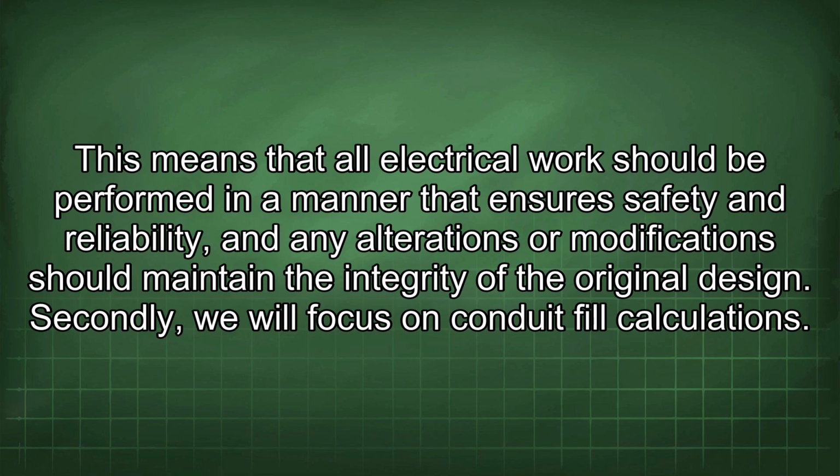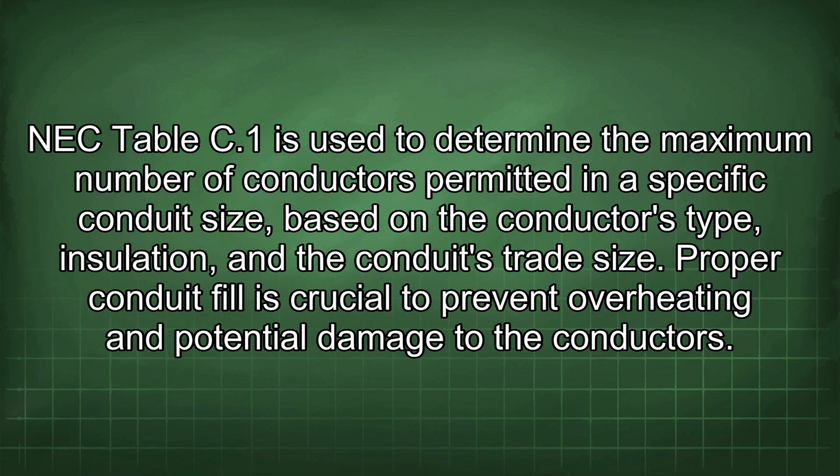Secondly, we will focus on conduit fill calculations. NEC Table C1 is used to determine the maximum number of conductors permitted in a specific conduit size, based on the conductor's type, insulation, and the conduit's trade size. Proper conduit fill is crucial to prevent overheating and potential damage to the conductors.